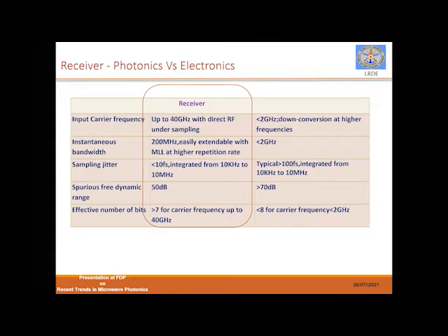What I meant is, finally these sampled signals go to the signal processing section. If our interfaces and signal processing are capable of handling data at a very high rate, I can have a bandwidth of even 10, sorry, not megahertz, 10 gigahertz. Then just imagine, if we are getting a sampling rate of 10 gigahertz, obviously your range resolution is going to increase drastically.